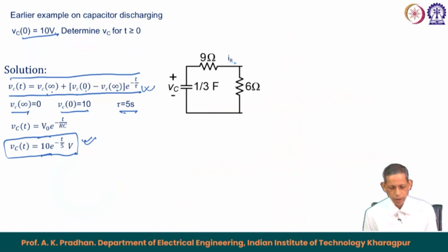What we would like to say is that this is a generic equation for voltage for RC, RL, and similarly the current expression happens to be the same for all combinations, whether it is source free or with source. For all cases we can apply this generic equation, and this simplifies our analysis to a great extent.